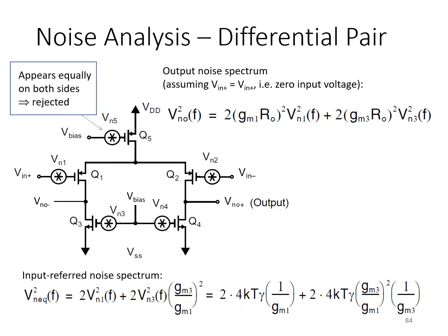We're going to start by doing a noise analysis for the simplest type of op-amp circuit, the simple actively loaded differential pair. You'll see that for all 5 transistors here, we've adopted the gate-referred noise model, where a single noisy voltage source in the gate of each transistor captures both the flicker and thermal noise. We're going to also at first focus on thermal noise specifically.